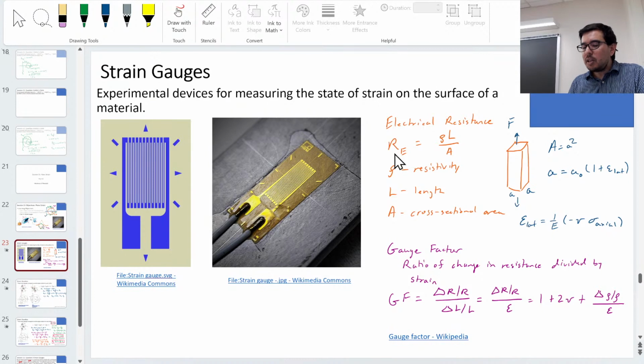It turns out that it's not just about the change in cross-sectional diameter with the materials that are typically chosen for this. You get increased sensitivity from a piezoresistive effect, so that the resistance actually changes. The strain actually induces a higher change than just the cross-sectional area changing. Either way, what's really nice is that we have devices that are not incredibly expensive, that you can attach to a pressure vessel or some other object, to be able to figure out how much strain it is undergoing.